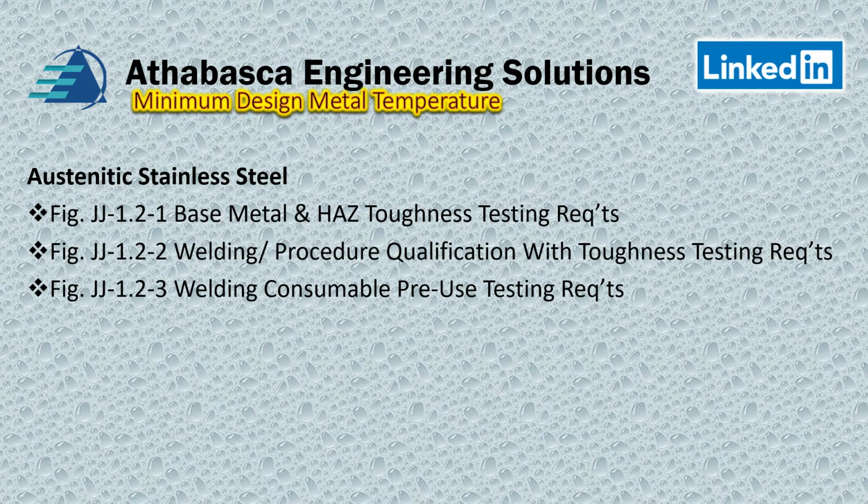Like, it has to have the correct, what they refer to as the ferrite number, and there's specific requirements for the ferrite numbers, and that's the big thing with stainless steel. So they have a separate section of that, and I think it's sort of tuned to the manufacturer so that they are meeting those requirements. And there's other standards, right, at SFA, and other ones that sort of confirm that. And then, of course, there's the production toughness requirements, which is part 4 for the stainless steel.